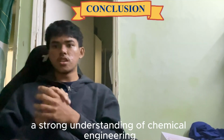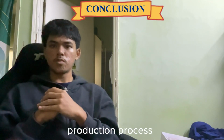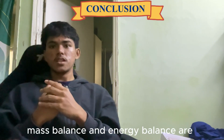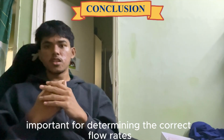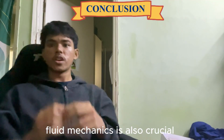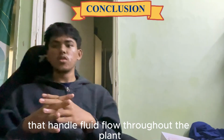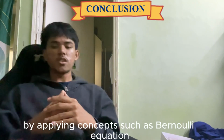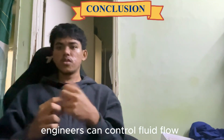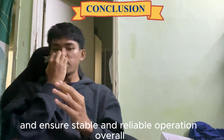In conclusion, a strong understanding of chemical engineering principles and fluid mechanics is essential in designing a cumene production process to ensure efficiency and safe operation. Mass balance and energy balance are important for determining the correct flow rates, composition, and heat requirement of each unit in the process. Fluid mechanics is also crucial for designing the piping and pumping system that handles fluid flow throughout the plant. By applying concepts such as the Bernoulli equation and pressure drop analysis, engineers can control fluid flow, account for friction losses, and ensure stable and reliable operation.